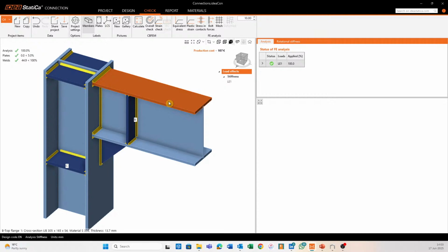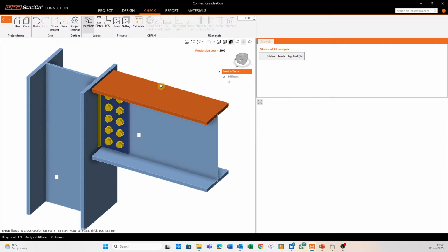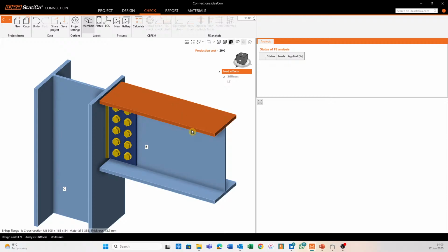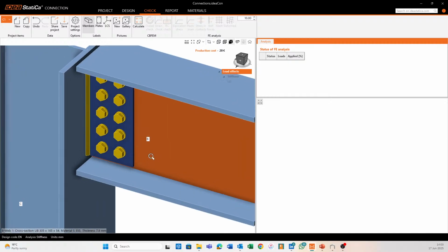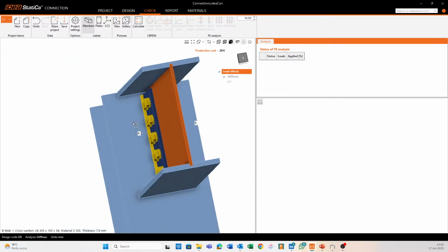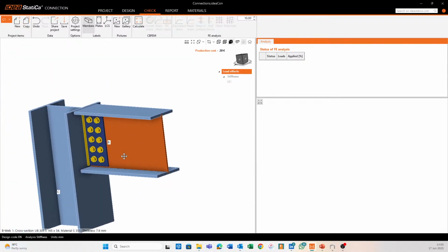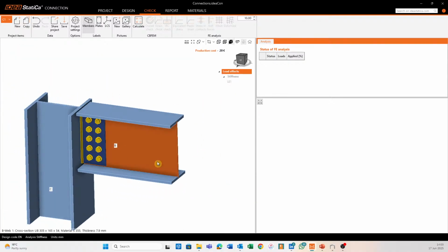Okay, but in reality, even a shear plate, so even if I go to C1, which for all intents and purposes I would take as a pinned connection, you know that if there was to be an imposed load here and this beam would bend, these bolts and this weld can actually transfer some of the moment forces.